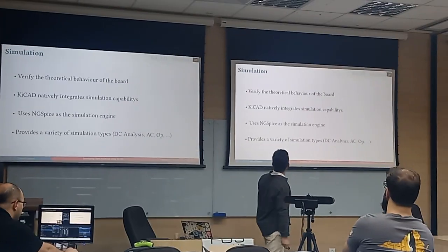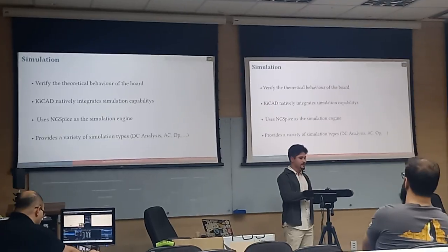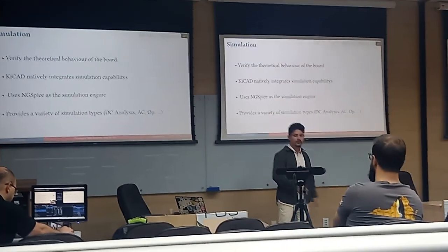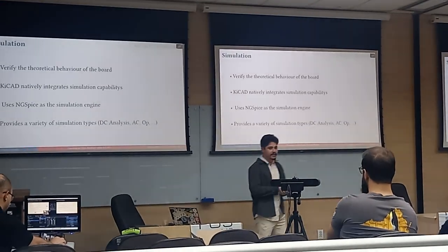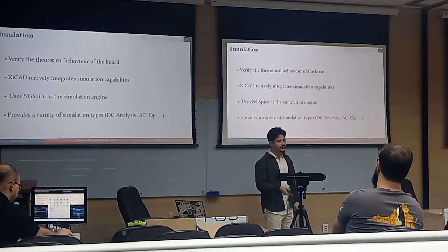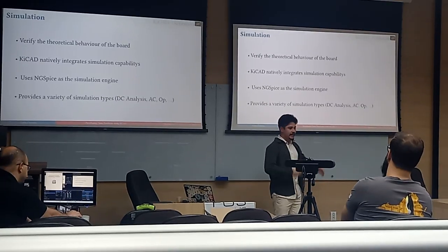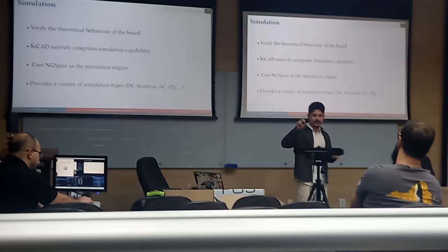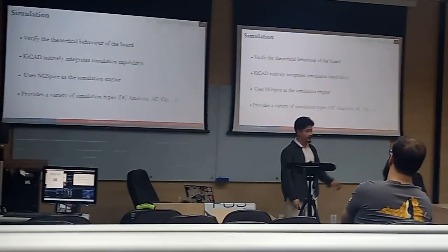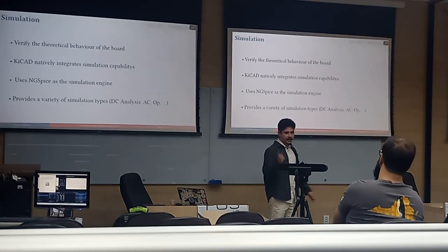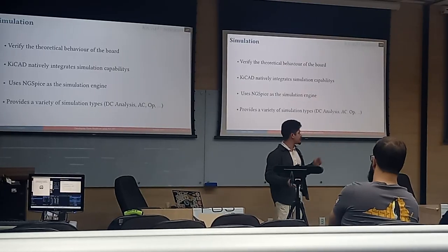So okay, KiCad also has a simulation, because we checked that we connected things right, but does it behave the correct way? Simulation goes with this, and one of the things that KiCad is very good at, and I think this is a recent feature that was not available in past versions, is native integration. You don't need to export a SPICE model and simulate in an external simulator. It's integrated itself. I used KiCad version 7. Version 8 is way better, but I will discuss issues with simulation at the end of the presentation.